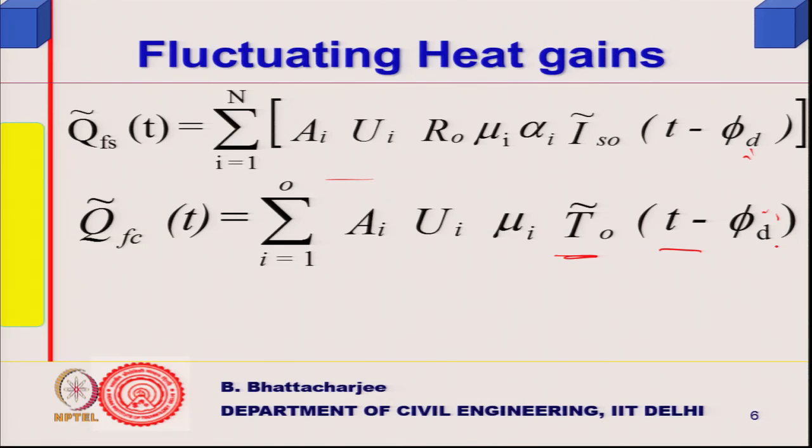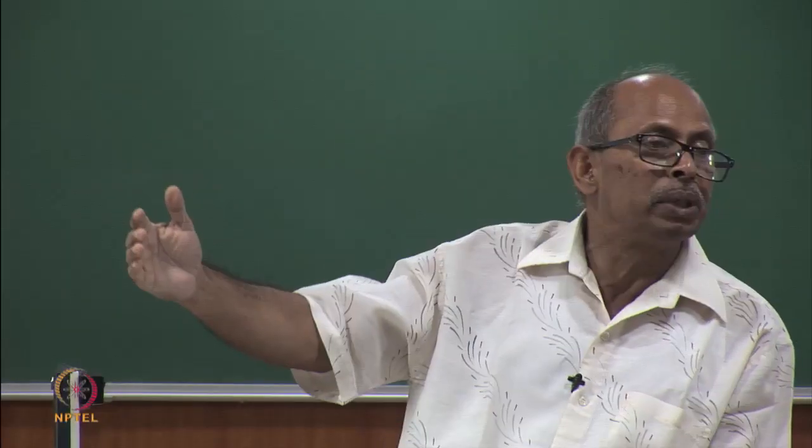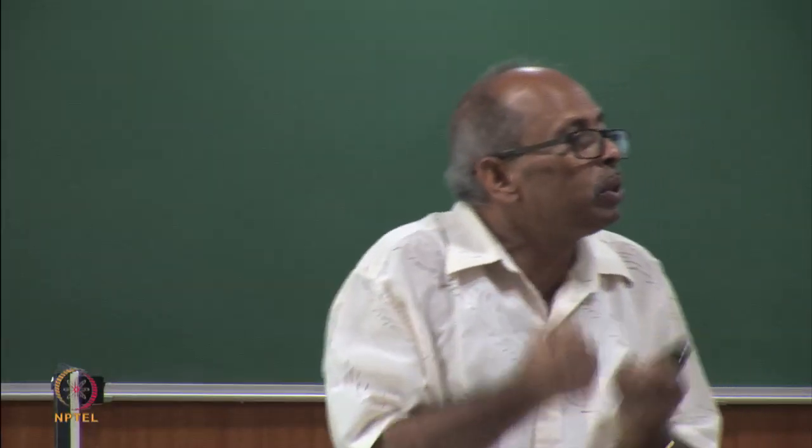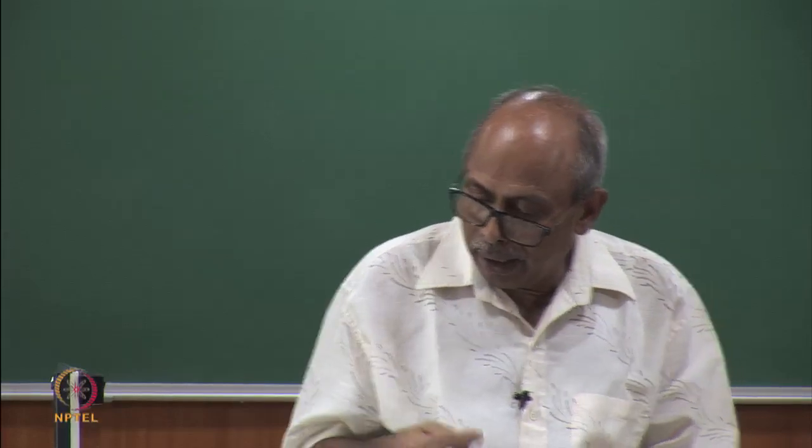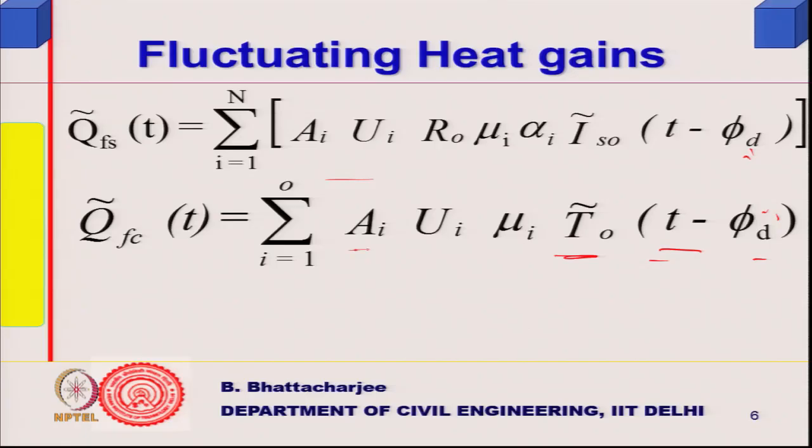That is how you calculate it in terms of time, because t minus this I will take. The temperature swing has taken place earlier outside, now it is coming in, because it will store and then transmit. And this term stands for the U swing multiplied by area and T swing. So, that is the fluctuating component of FCT, the conduction gain because of outside temperature.